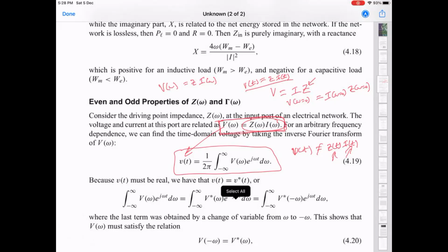So then it makes a lot more sense that if I'm talking about a voltage at a particular frequency, then it must be the current and the impedance at that particular frequency which matters, which seems to go back to the basic Ohm's law, which has exactly the same form and we have been using, but without really thinking about it, that it's actually talking about frequency space, except that it's zero frequency. So the more fundamental Ohm's law holds true as the more core equation, provided you are considering them for separate frequencies separately.